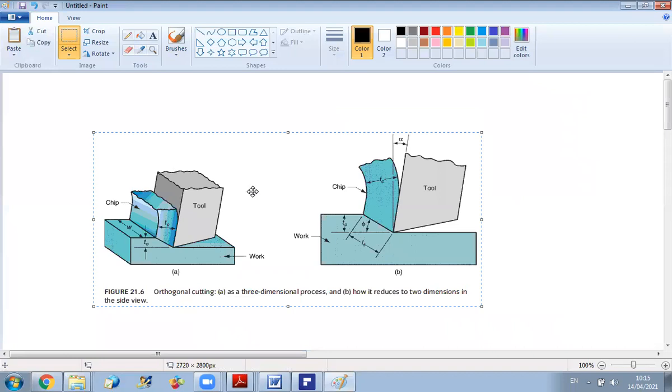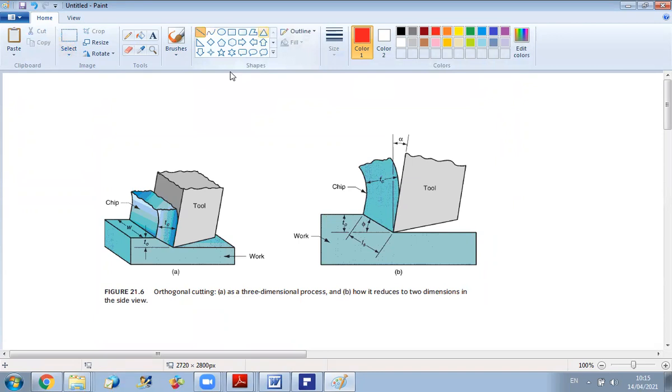Yes, doctor. Okay. So my purpose is to determine T0 over Tc as a function of the angle. If you look at this figure, this is T0. If we call this distance Ls, it is the length at the level of the shear plane. We will see that this length will be simplified in the ratio.